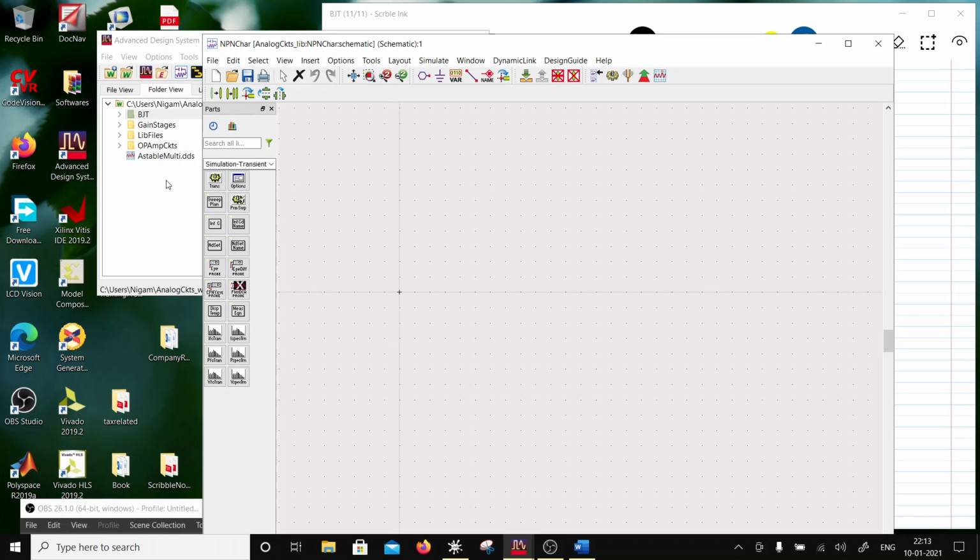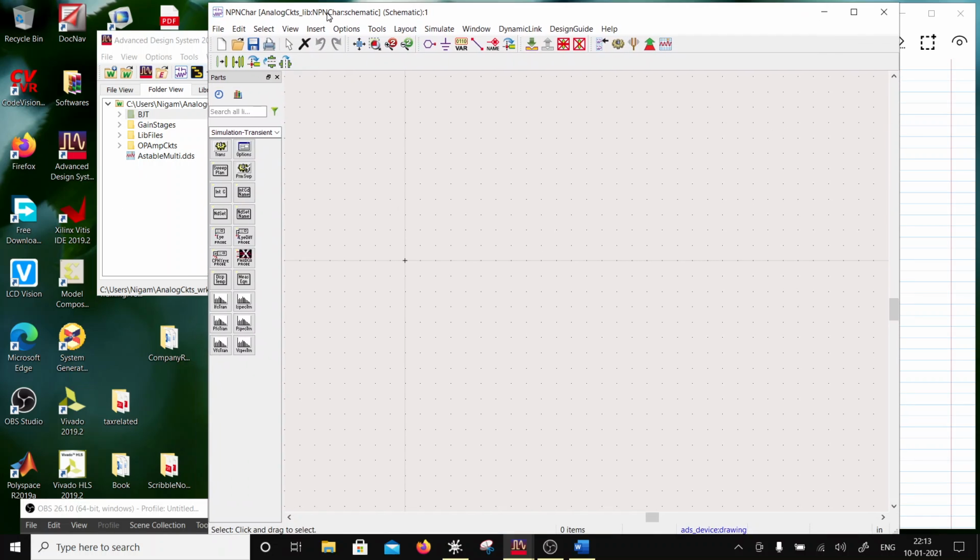Okay, so there are a number of models for devices. For example, for FinFETs we have been using BSIM-CMG. For some of the MOSFETs which are like 130 nanometer, we are using BSIM-4 models. For IO devices we are using BSIM-3 models. And for a bipolar, the simplest is a Gummel-Poon model. Then there are certain other compact models like Vbic, right? So we are going to use a Vbic model in here.